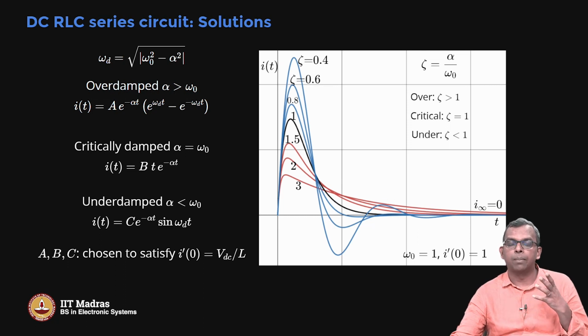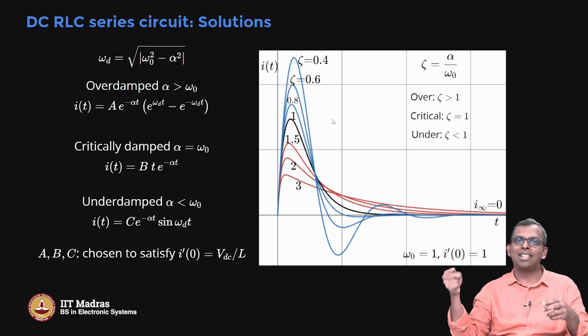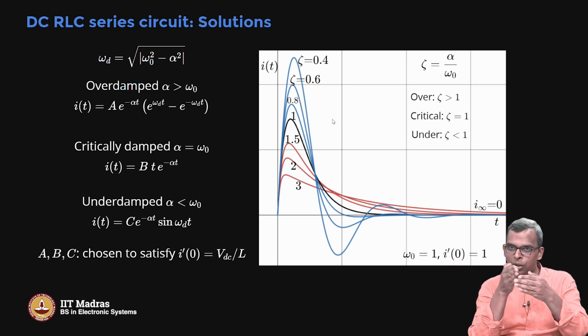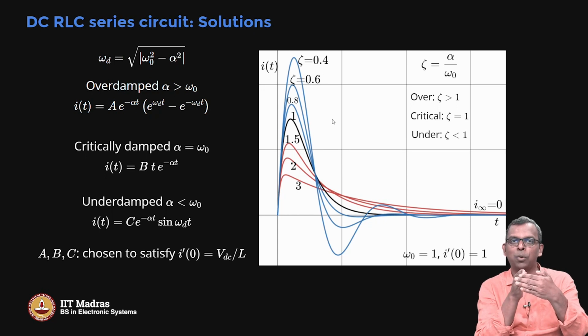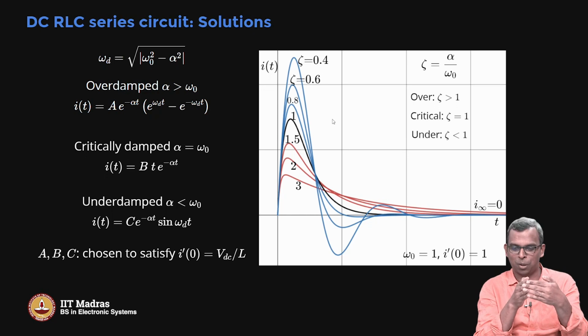So, a second order system with DC input, with just an initial input and then you let go, do not give anything else, it will eventually die down to 0. How quickly it dies down depends on these parameters. If it is underdamped, it is going to go to both sides. For instance, from the door analogy I gave you, if you are underdamped, the door will go close, go past it to the other side, come back and then settle down. You might have seen some doors like that, no? When you pull it out, it will go this way, that way, stop.